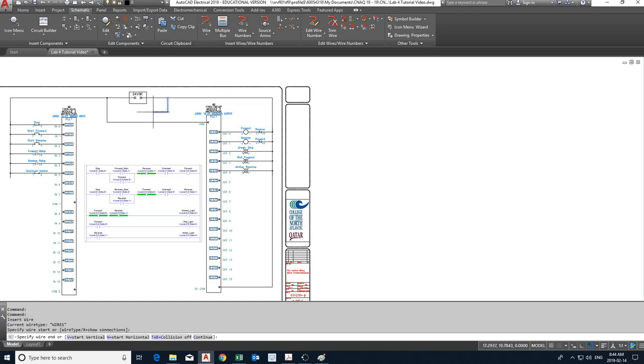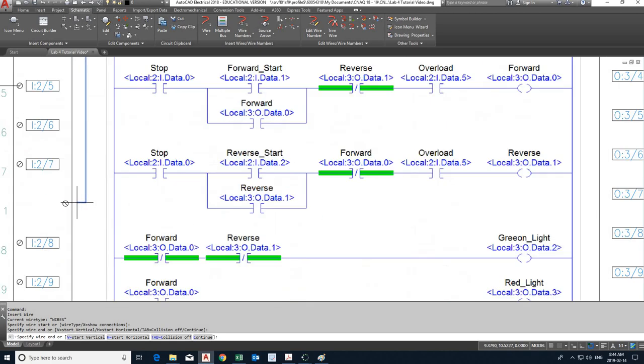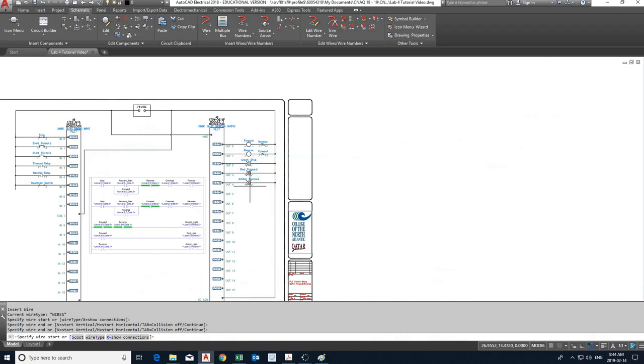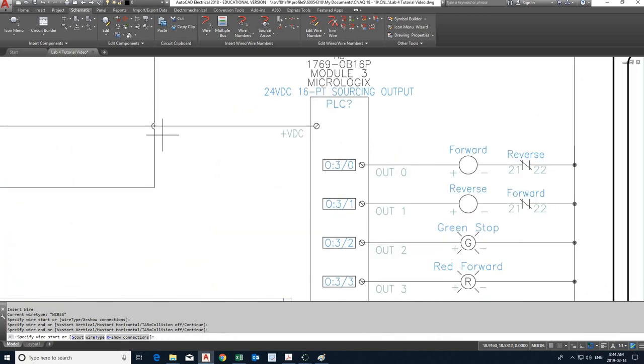So I'm going to come here and click somewhere like that. Zoom in and catch the quadrant. This is slightly different than here. Doesn't matter. The important thing is the electrical details. It's not so much that you have to replicate it exactly the same. The point is there's a wire going from the negative terminal to that point. Notice AutoCAD also automatically introduces this half circle, meaning there's no connection between these crossing wires.